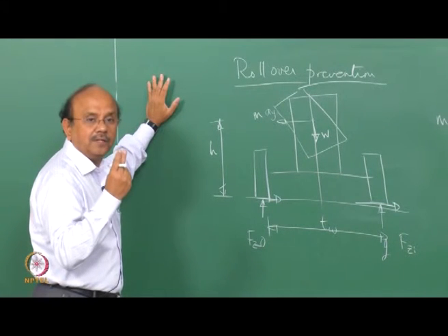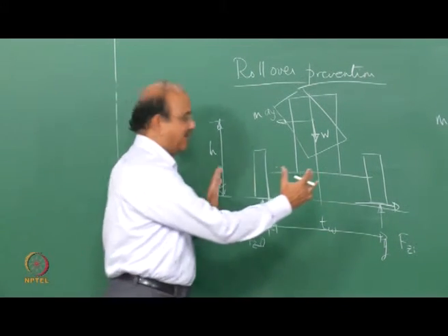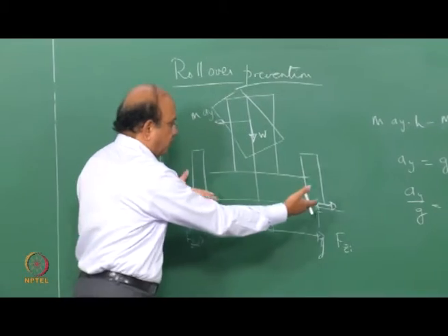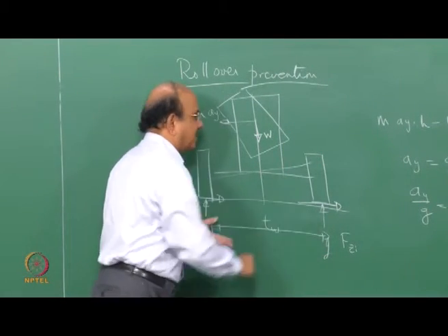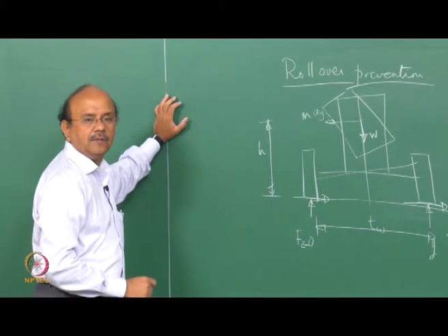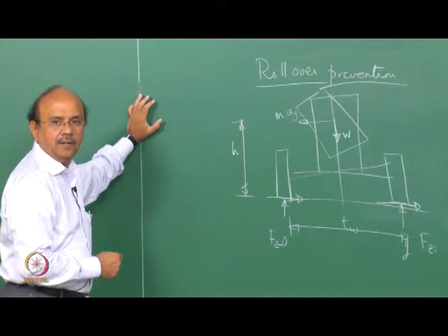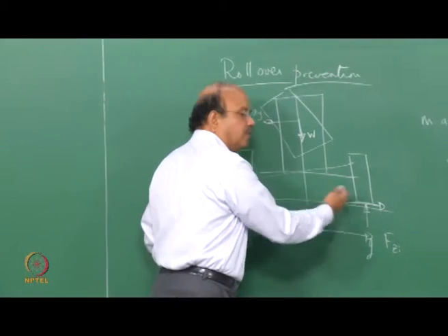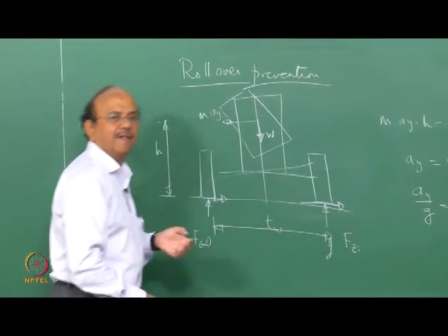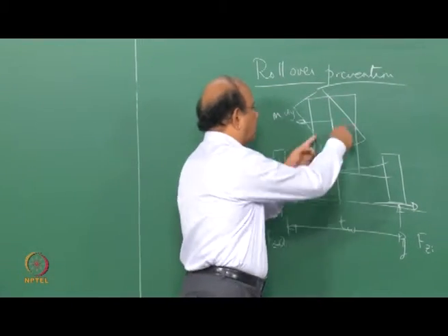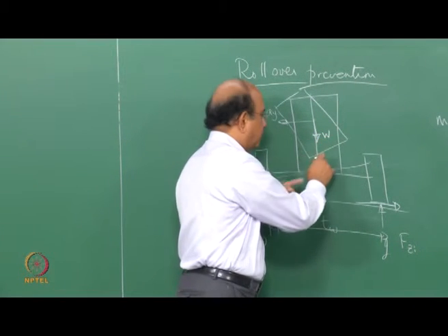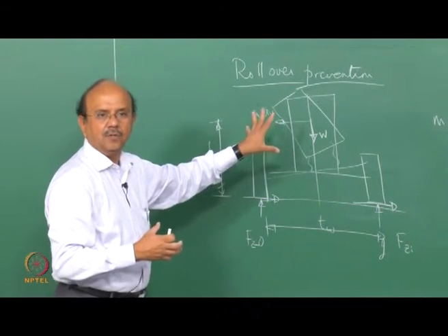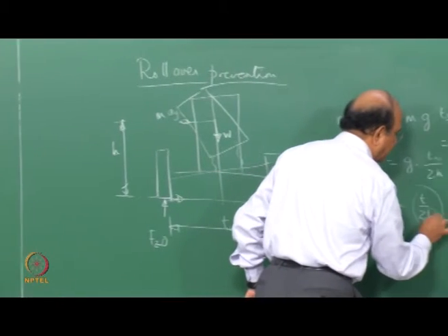There are two rolls here. One is the roll of the unsprung mass, which is basically due to the tire stiffness. Let's look at this suspension system or this axle system, which is a rigid axle system, which is there in most of the commercial vehicles. So because of this, it is going to be affected. And the second one is that on top of it is going to sit this sprung mass, and that sprung mass is now affected by the roll stiffness.